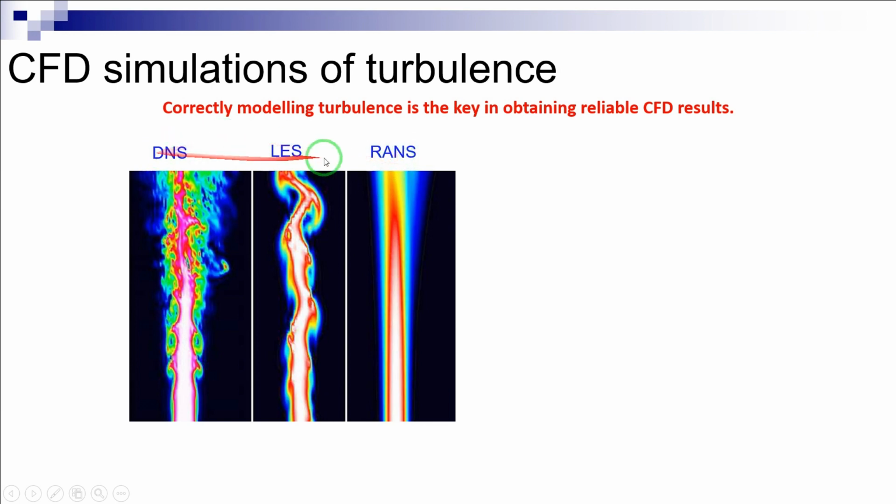The RANS equations arise from ensemble averaging, not time averaging of the Navier-Stokes equations, in which the instantaneous flow variables are decomposed into the mean and fluctuating parts using the Reynolds decomposition technique. In these equations, the turbulence effect is represented through the Reynolds stresses, which are modeled by turbulence models. In other words, the RANS equations provide the mean flow characteristics, where the turbulence effect on these mean flow characteristics is accounted for through turbulence modeling.